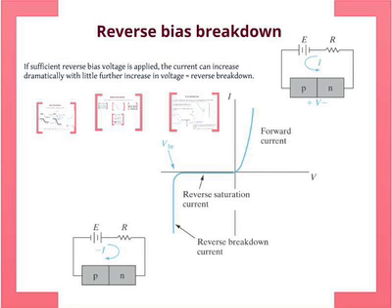So if I were to draw the current-voltage characteristics of a realistic diode, you see current going up exponentially with voltage, we know this, and current here being very small, which is pretty much independent of voltage. This is what we know now. What we're going to say is that when you apply sufficient voltage, this can break down, which means you can have very, very large current flowing here at a fixed voltage, pretty much, the so-called breakdown voltage. So this regime is what we've seen so far. This regime is what we're going to talk about. Okay, so keep that perspective in mind.